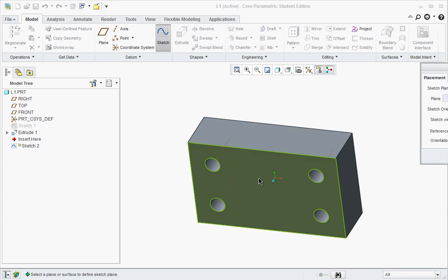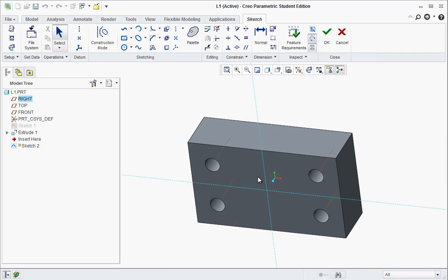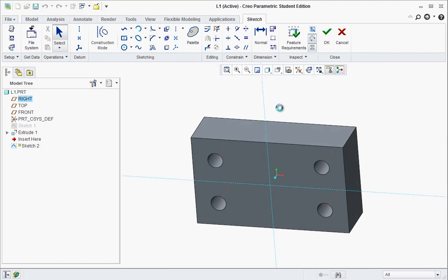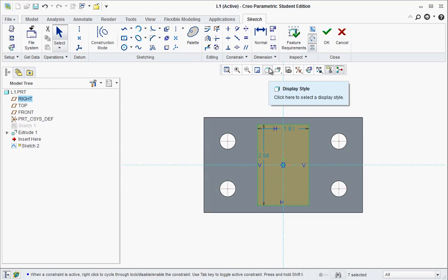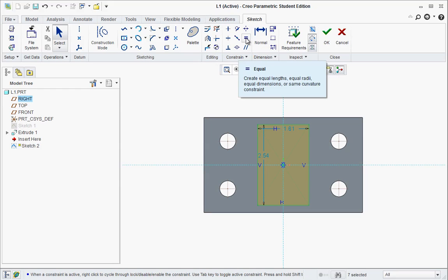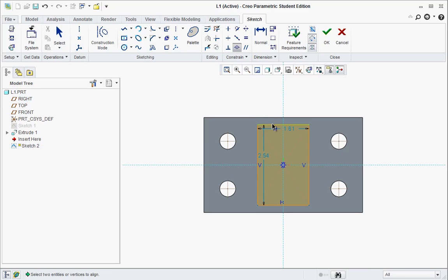Now we could start another sketch on the front face of this. And I'm going to go to AB front. And again, we could use our center rectangle tool to draw this out. Now notice we're not capturing the edge again. Remember the trick to that. Drag it close to it, a little bit distance away, then middle click a couple times. Now you could go to the coincident tool, the little eyeball. Click on that. Select this edge, either the top or the bottom, it doesn't matter, and then the closest edge to it on the actual solid. And then it aligns itself to it.